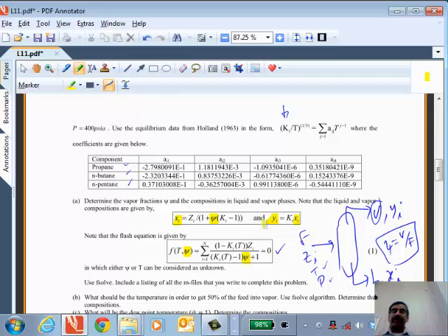And what is the composition in the liquid. Unfortunately, what happens in real life is the temperature is something that you don't know beforehand. Maybe you want to control it. Okay? Meaning I want to adjust the temperature in such a way that 50% of the feed goes as vapor. In such a specification, what I'm telling you is I know psi, but I don't know what the temperature is.